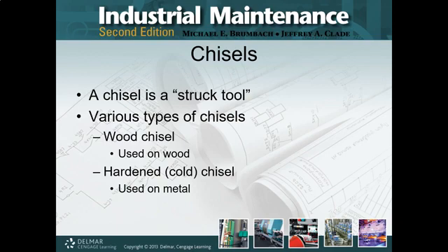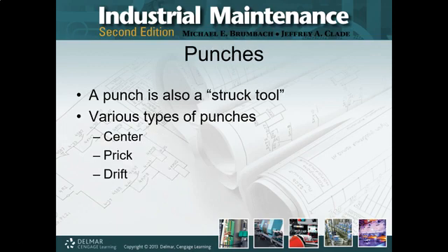And anytime you use a wood chisel or a hardened chisel, please wear eye protection and hand protection. As I promise you, maybe not the first time, but at some point, if you don't wear that, you are going to have a problem. So don't be that problem.